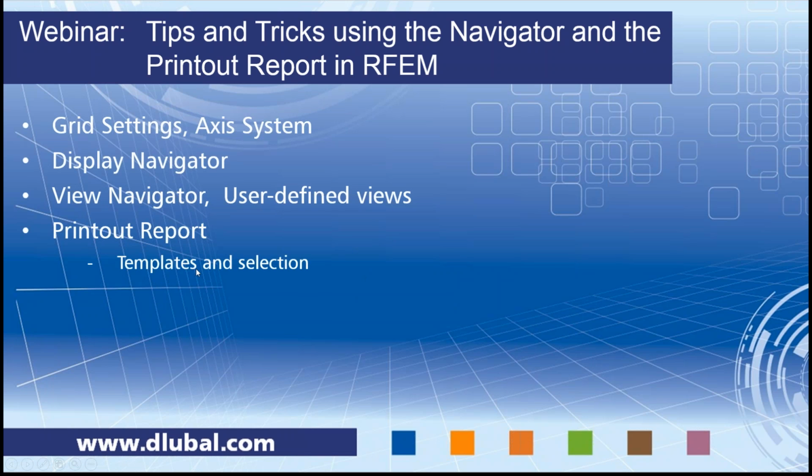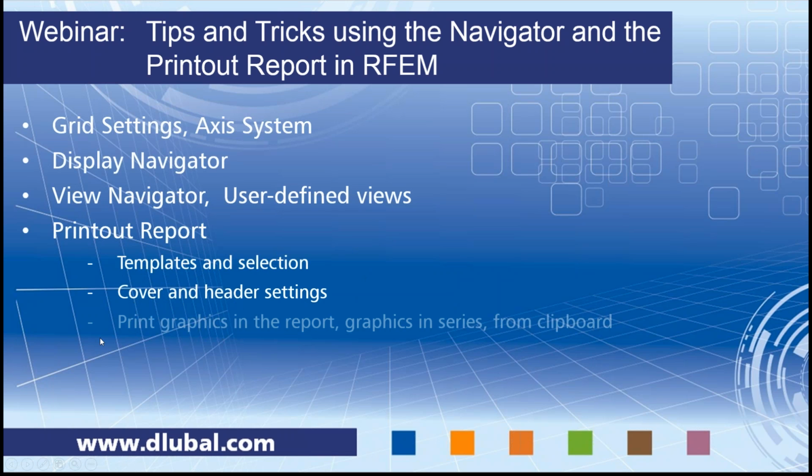So we will use templates and define our own templates, change the selections. We will create cover and headers, and we will print graphics into the report. We will also have graphics in series, and we will insert graphics from the clipboard. And finally, I will open another RFEM file where we use the template that we created earlier. And in another three-dimensional model, I will show you how to use the three-dimensional PDF.